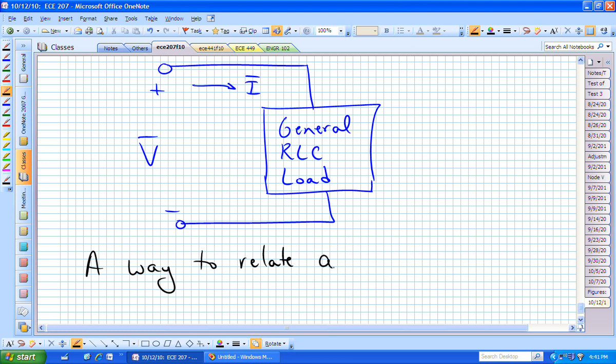Because we have apparent power, we have real power, which is average power, we have reactive power. The units on apparent power are volt amperes, VA. Real power or average power, the units, watts. The units on reactive power, volt amp reactive, VARs or volt amperes reactive. Okay? So let's now relate all of those.